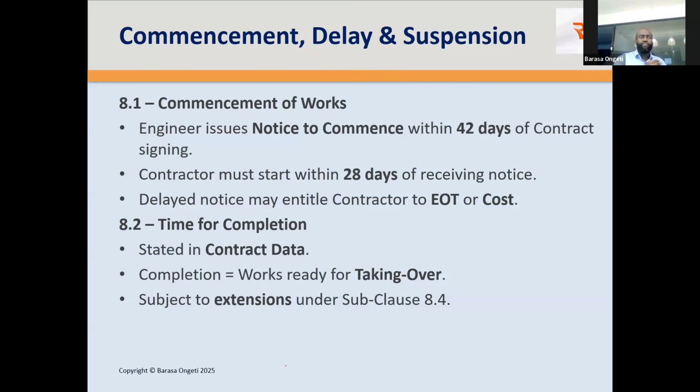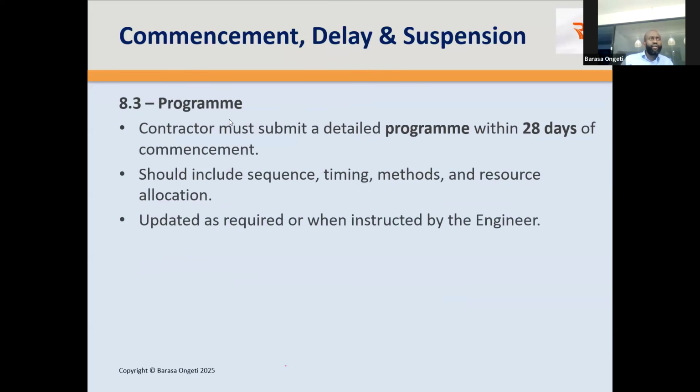For example, if it's a road project and you say that the test is a deflection test, perhaps on the surface of the road, using the Benkelman beam or whatever it is you use in your road projects, if you use the Benkelman beam and the test passes, that there's no deflection on the road, the works is ready for taking over. That's just an example. Now, time for completion is subject to extensions under subclause 8.4. We'll be looking at that shortly.